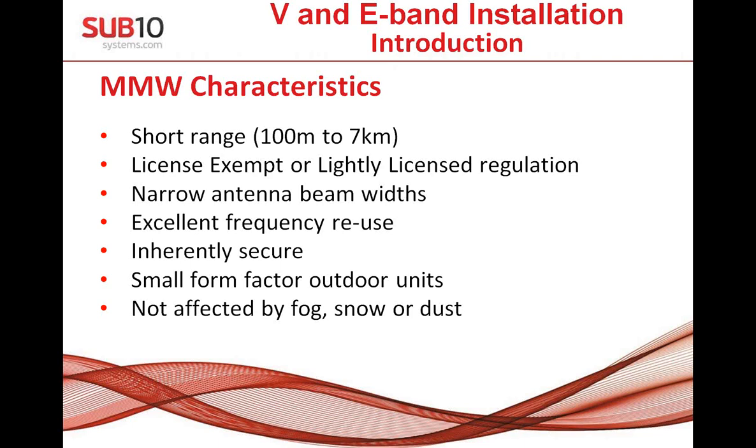It's a very compact device which can be installed even in windows or close to windows on buildings, and you can really easily make it hidden from people, which is really important, especially for city installation, where some local municipalities say, okay, you can install a point-to-point link, but there will be no visibility, no antennas, and so on. And compared to mainly laser technologies, these systems are not affected by fog, snow, or dust. Only rain has to be calculated during the link budget preparation.